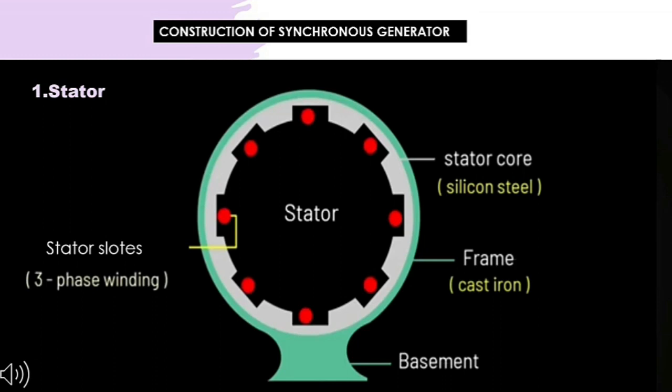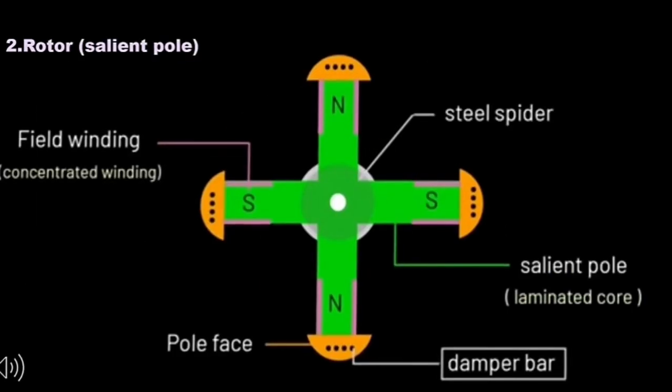And there is the stator core that is made up of laminated silicon steel that has high permeability and provides low reluctance path. The meaning of lamination is the stator core is an arrangement of various thin sheets, provided with lamination to reduce eddy current losses. At the inner portion of alternator, slots are provided where three-phase winding is placed in star connection. When coils are added in series, it is known as a winding that is placed in the provided slots.